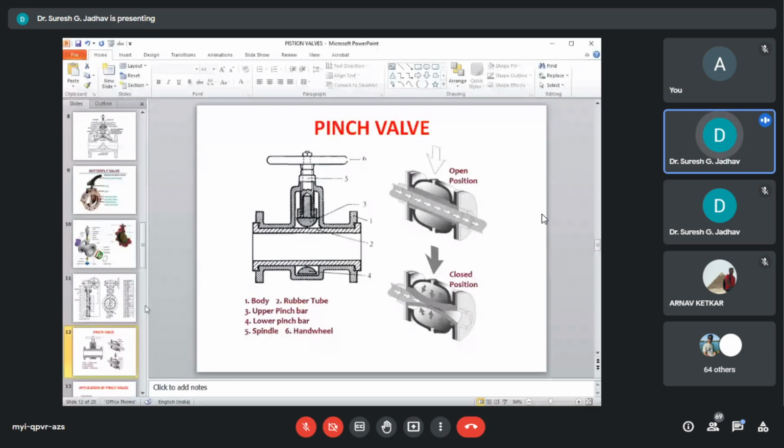So pinch valves are of two types: one is the open pinch valve and the second one is the closed pinch valve. Mechanically, open pinch valves are usually of open type without metal body casings. The open construction of the pinch valve is used for inspecting the valve body visually and physically during operations. This is the most simple design, but the liner is exposed to the environment.